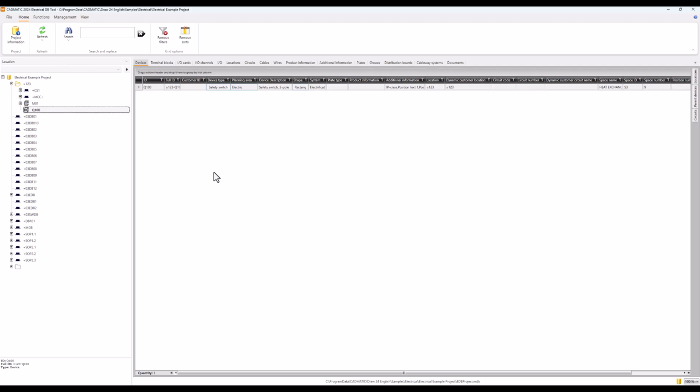If you had your database closed, made changes to the drawing, then saved the drawing, and after that only started the database tool, of course in that case you don't have to refresh, because when the database tool is opening for the first time, it will read the actual database. So keep in mind, this is only a tool to inspect and do modifications to your database. This isn't the actual database. This is not Access, only a tool to do modifications.